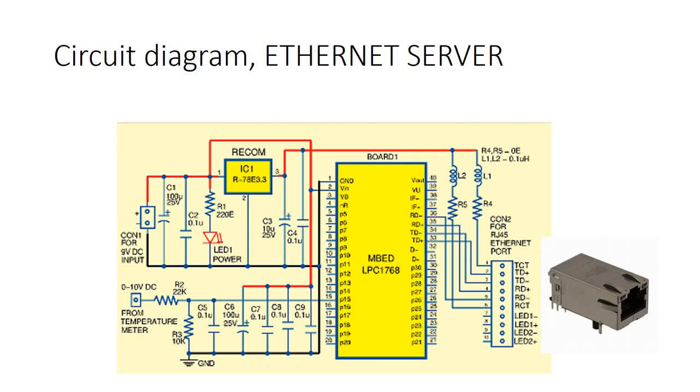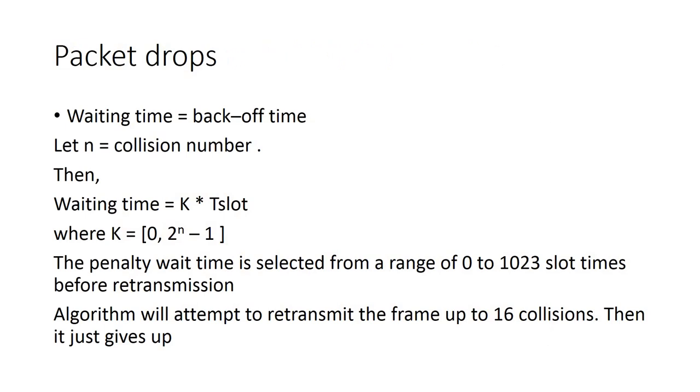You can simply connect a single supply of plus 12 volt, or plus 5 volt or 9 volt, into the system, and suppose you are giving the voltage input, you are reading from a 0 to 10 volt DC output of a commercial temperature meter, proportional to the temperature from a sensor. So this device takes the voltage and converts it into an Ethernet server, the voltage to Ethernet server, something like that. It's like a voltage server, you can say, to read the temperature.